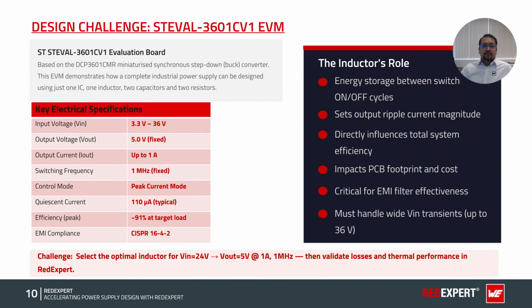As you all know, the inductor plays a critical role here. Finding an optimal inductor is definitely a challenge, because the inductor sets the output ripple current that directly influences total system efficiency. It also impacts PCB footprint and cost, and it is also critical for EMI filter effectiveness. So let's dive into this and find an optimal inductor for this particular design.